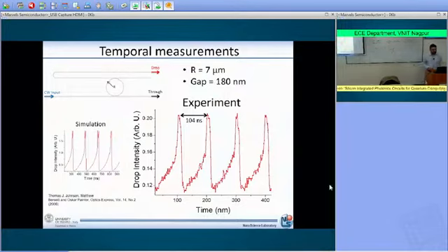So what happens in the microring resonator is that now, with a CW input power, a constant input power, the transmission in the drop port is pulsing, okay? Because of those two effects. And so we have an effect that is called the self-pulsing effect. The microring resonator transmission starts to pulse even though the microring resonator has been fed by a constant beam. And this is something that you can simulate or even experimentally observe.